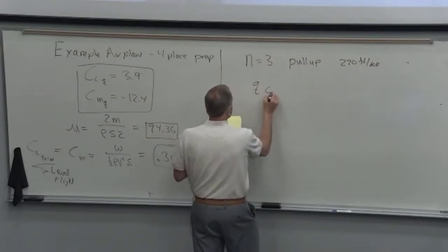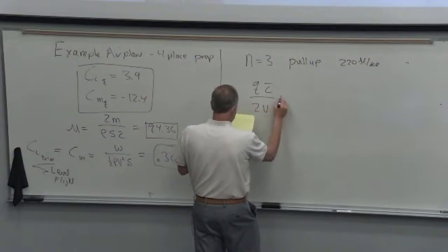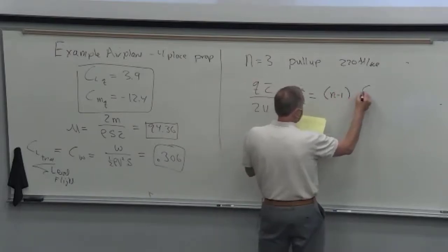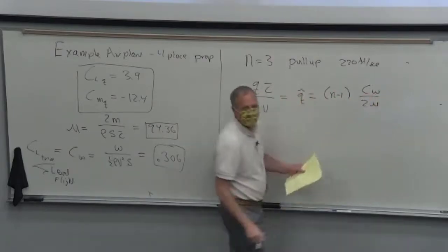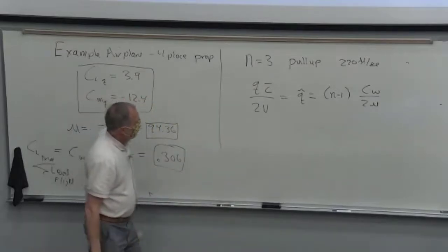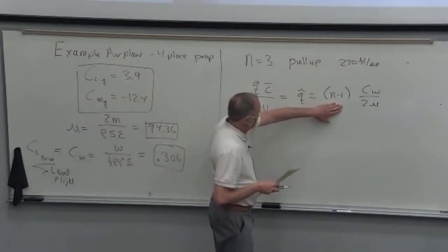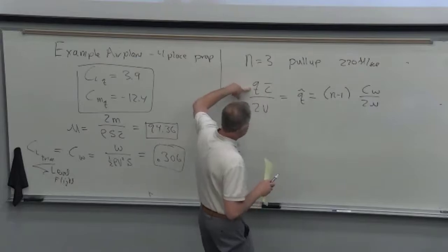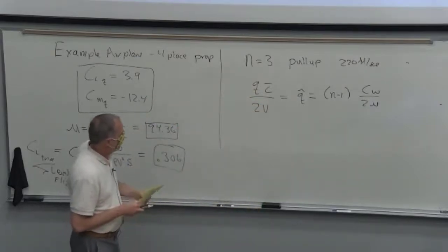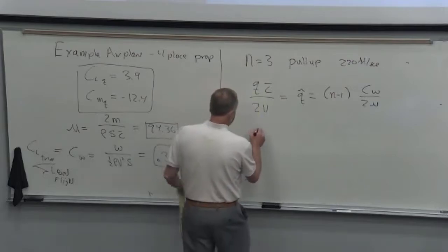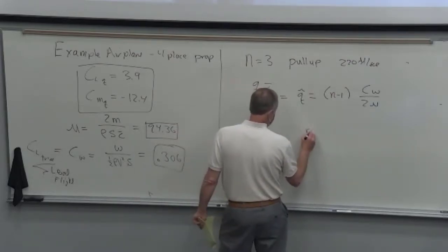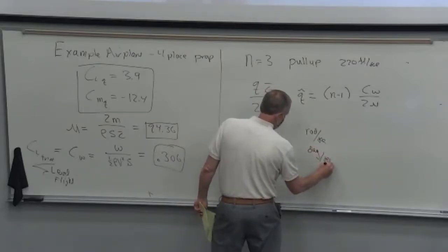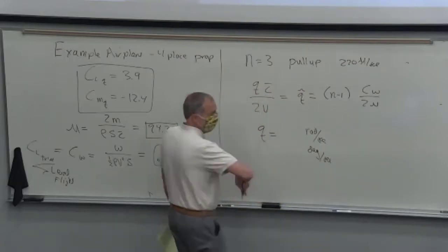And so I want to calculate Q. And what we have is this non-dimensional Q in terms of load factor. So there's why we needed CW. We calculated this by plugging in Q into this formula in terms of load factor, and we got that. So let's calculate this. What is this thing? Because that's going to give us radians per second, and then we're going to convert it to degrees per second, and then we're going to find out how long it takes to go a full 360.